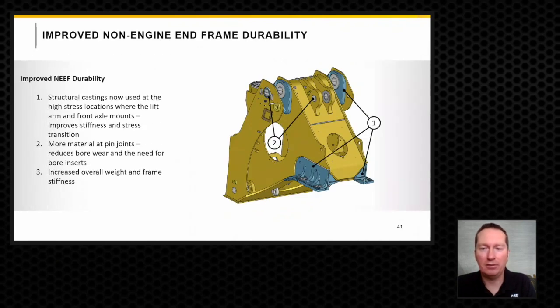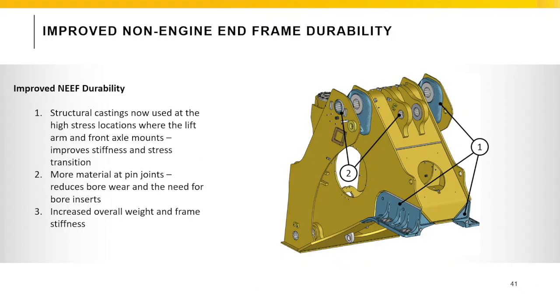The front frame, this is an all-around solid design. Just a couple of things to point out. If you look at the way that that front end is closed in, that does a nice job to create torsional rigidity. And looking up at the castings at the top, the engineers on this frame did a nice job managing that load path.